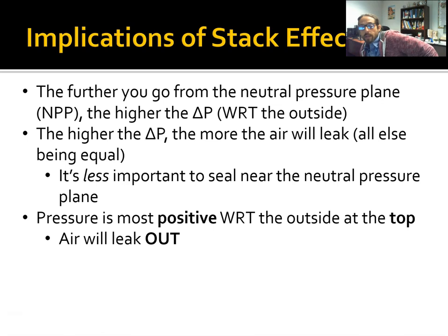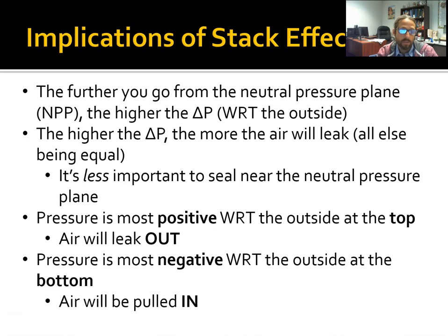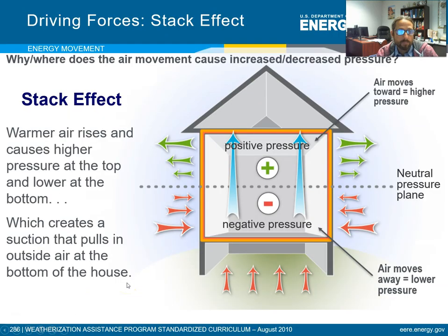And so at the very top, that's where you're going to have your biggest positive pressure. And so that's where you really need to seal at the very top of the building, because air is going to leak out there. And then at the bottom, you're going to have a very negative pressure, which means air is pulling in. And so you definitely need to seal toward the bottom as well. Okay? So that's the stack effect in a nutshell.